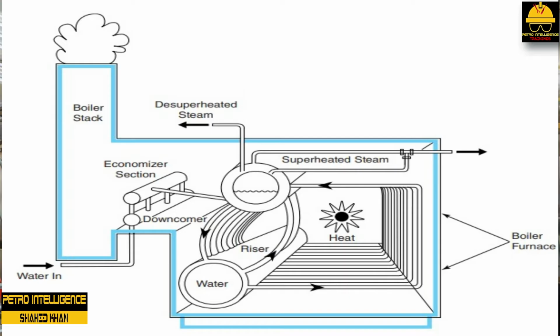The riser and steam generating tubes are physically located near the burners. Steam moves up the riser and steam generating tubes and into the upper steam generating drum. Steam generation causes pressure to rise. When the target pressure is achieved, the boiler is placed on the line. Pressure is maintained by adding makeup water and continuously applying heat.